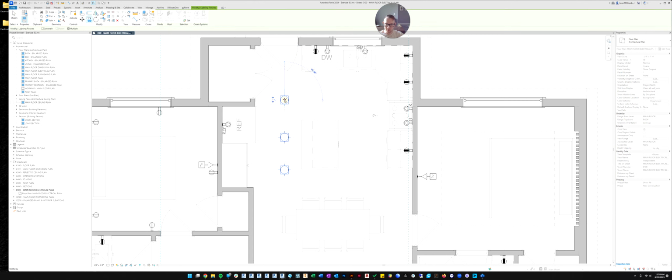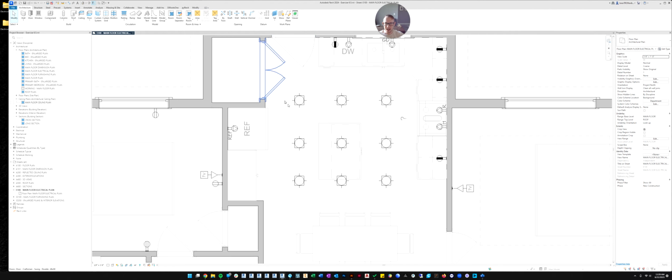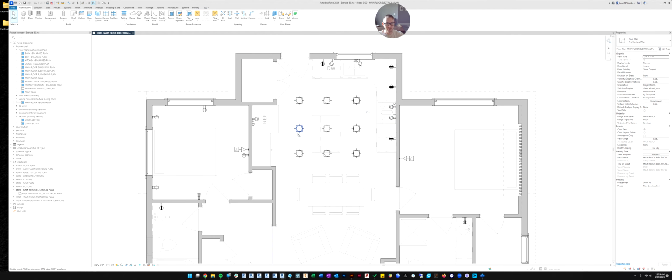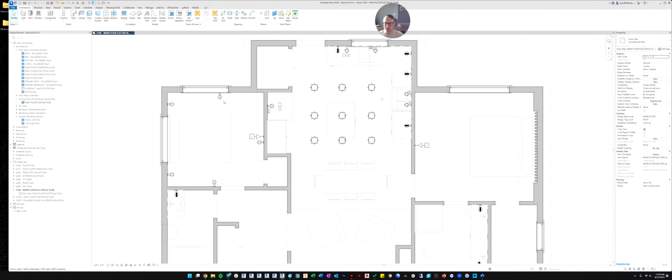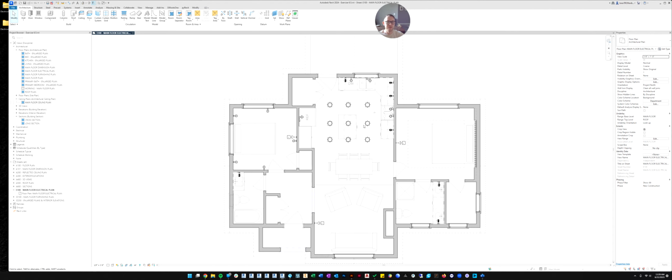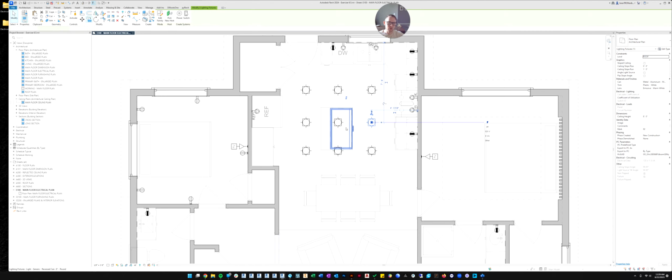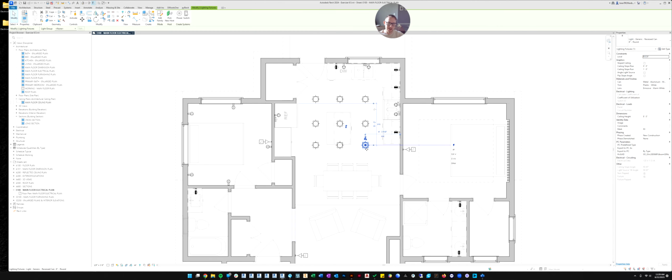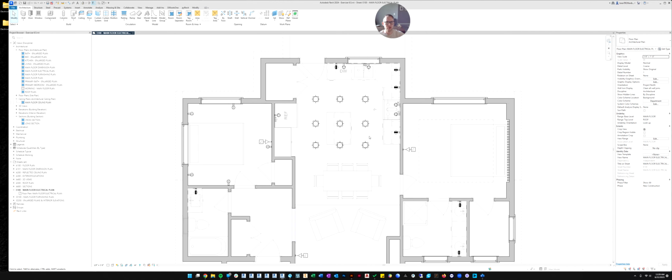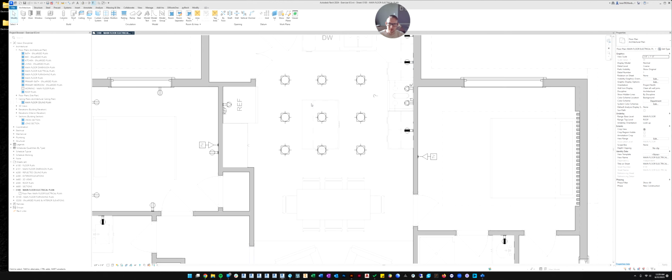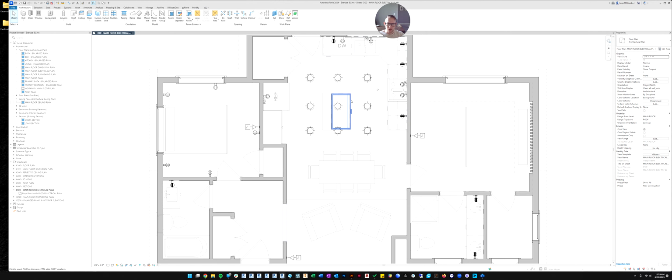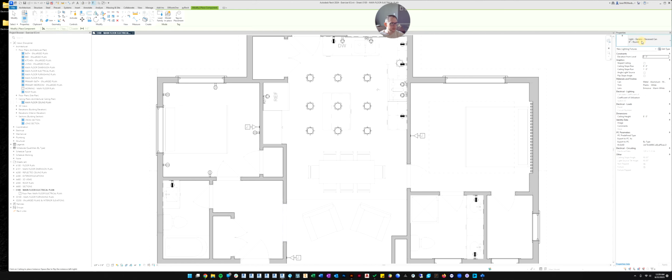And so we'll copy that over. And also notice that we're in a floor plan and they show up as black instead of half-toned. It's nice and black, just like the rest of the outlets. So graphically, these look much better. And we can also be in the floor plan and look. Now you can move these around, no problem. You don't have to go back to the ceiling plan to try to adjust your lighting layout. Okay, so there are the can lights. Let's put in our pendant lights. We'll go back to component and we'll search for pendant because we loaded in a pendant.